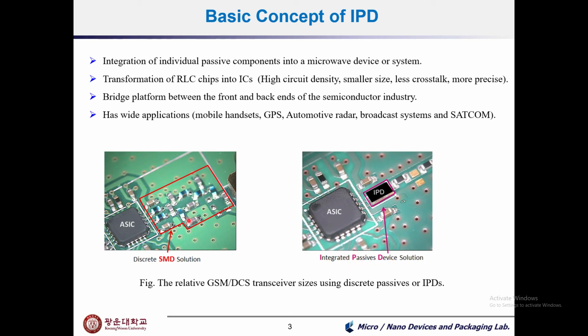We can see from these figures that in the discrete SMD case, a large number of passive components are distributed along this board, and if we see the same number of RLC components using the IPD technique, we can see how the size is miniaturized into a single IC.